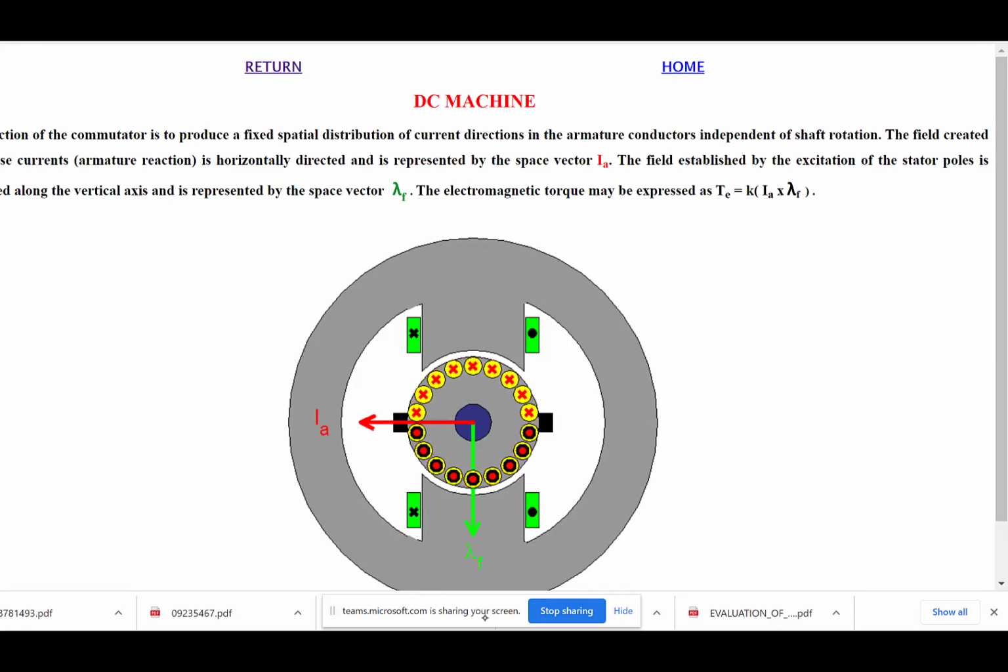we have the flux that we talk about, and this becomes very important in controlling motors, because controls are based on this. But you can divide the flux into two quadrants. You've got a direct axis flux, which is going down the direction of the green arrow. That's the D axis. And then there's a quadrature, which is in the red arrow, the Q axis.